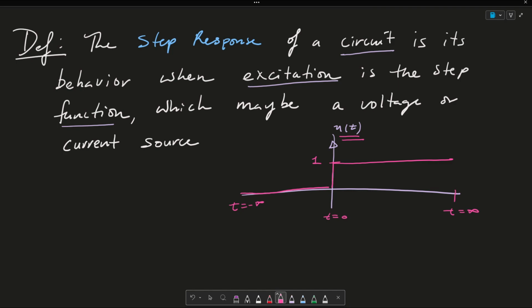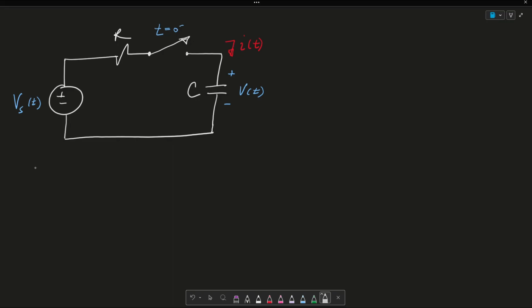So let's go ahead now and dive into the two cases that we want to evaluate. For the first part, we want to look at case number 1, essentially when t is less than or equal to 0. And again, this is when t equals 0 minus, or t equals 0 plus. The reason why these are the same is because the voltage of a capacitor cannot change instantaneously. I've talked about why this is the case in a past video I made, which I will post in the top right hand corner of this video.